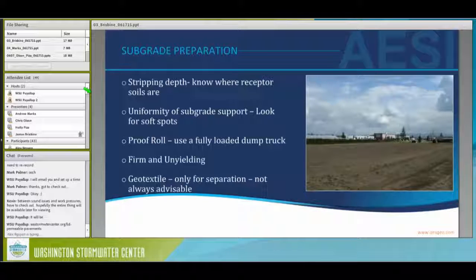When you're looking at infiltration, you'd like that subgrade to be as porous, as permeable, as loose as possible. So we're caught in our own struggle here to maintain pavement support, but also to maintain infiltration for the subgrade. So we're just playing a balancing act in terms of what's the minimum amount of compaction that would be acceptable to support the subgrade. There was a question earlier about whether you could put uncompacted sand below a pavement.